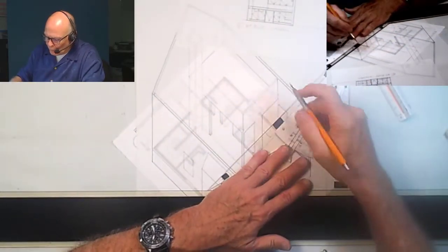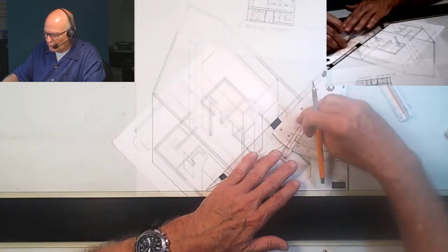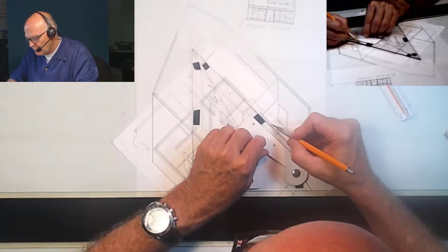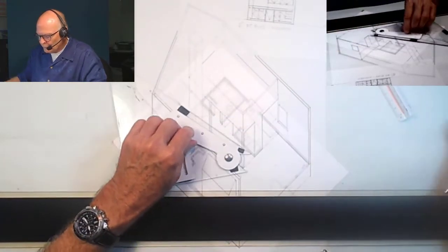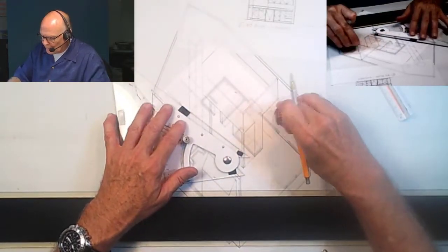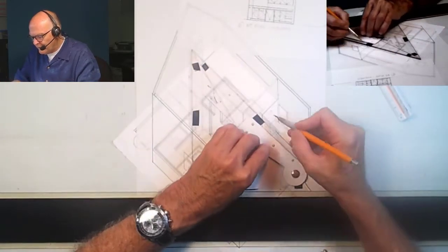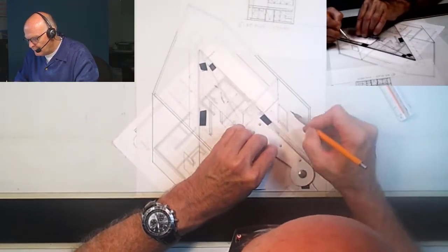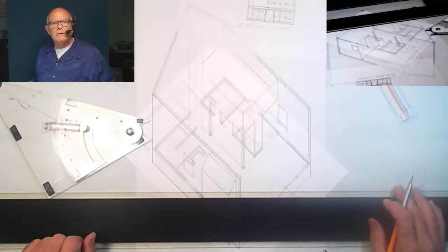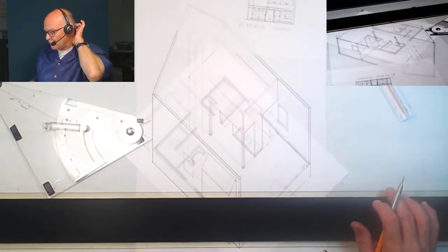And as before, all those horizontal lines are going to end up on a 45. So we're going to shoot those lines around here so that we can get rid of some of those other lines so they don't confuse us. Okay, so there's our basic box of the base cabinet, and it extends until we can't see it anymore. It goes underneath, and we'll fix those lines up in just a bit.